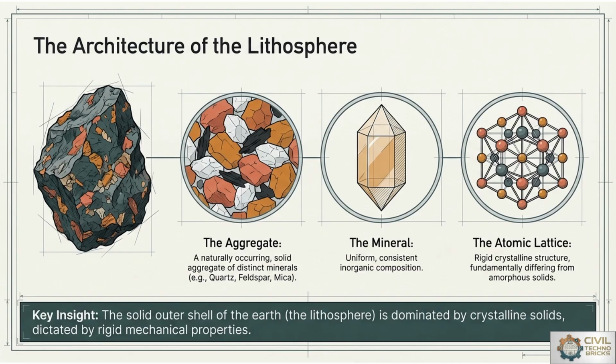These microscopic characteristics influence the mechanical properties of the lithosphere or the surface. It means rocks are aggregates of one or more minerals. A mineral possesses a definite chemical composition and crystalline structure, so the engineering characteristics of rocks depend on their mineral composition. So knowledge of minerals, from a civil engineer's point of view, is most important to check the assessment, durability, weathering resistance and strength characteristics.